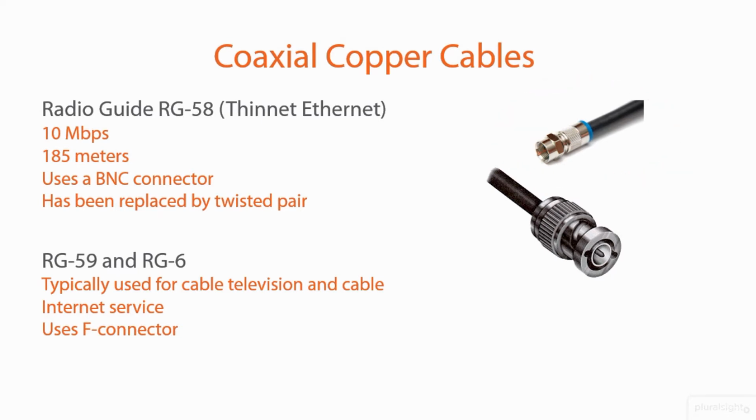Sometimes it can be difficult to screw down and tighten the connector, especially if you're in a constrained area like behind a high-def TV and you can't really see what you're doing, you have to go by feel. Another problem with RG59 and RG6 cable is that the inner copper conductor is pretty thin, and it can be easy, I should say, to accidentally bend that pin. You want to not do that wherever possible.